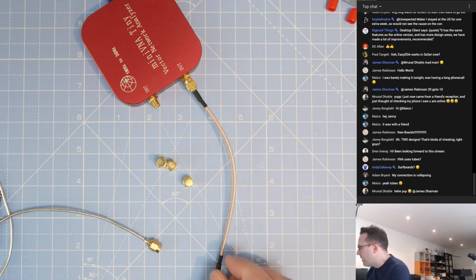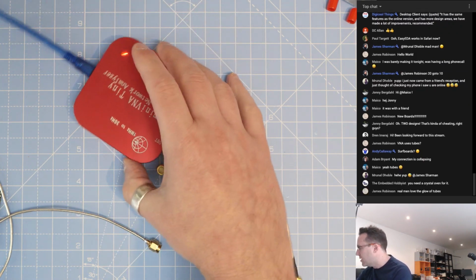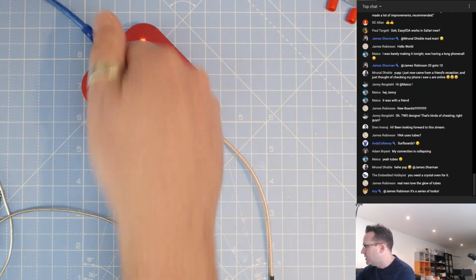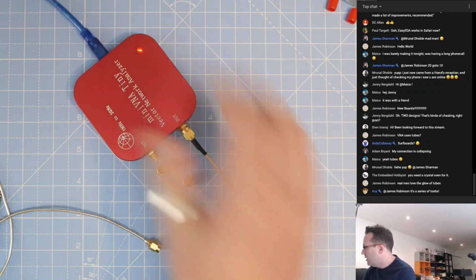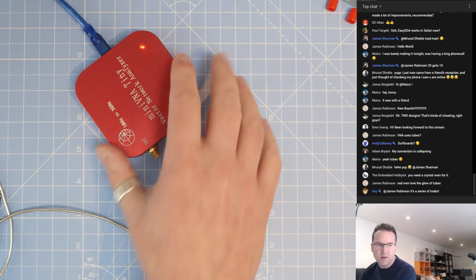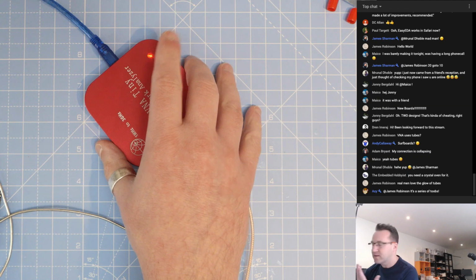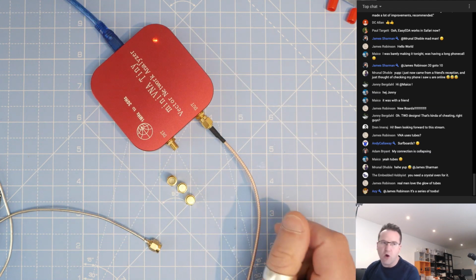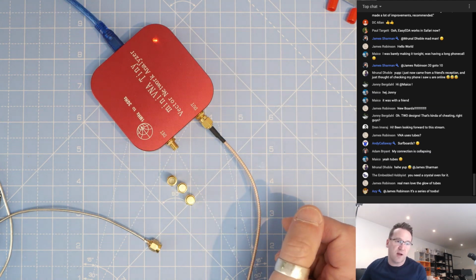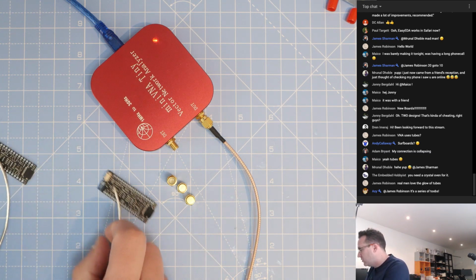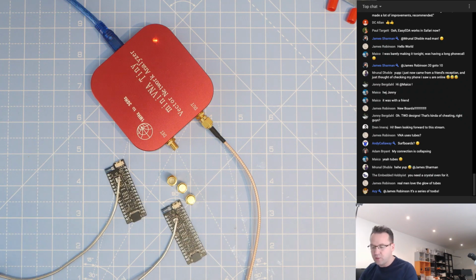Right, I need to do that, but I need to let the VNA warm up first. They recommend 15 to 20 minutes. It's been on for about 15 minutes, and I can feel it starting to get warm. So I'm just going to let it sit for another 10 minutes or so before I calibrate. I'll do the calibrate pass again like I did last time, so you'll all get to see that. It's not overly exciting, but it's a process I have to do. And then, yes, I've got 2 boards to do. But while we're waiting, I'll show you what I did with the boards.